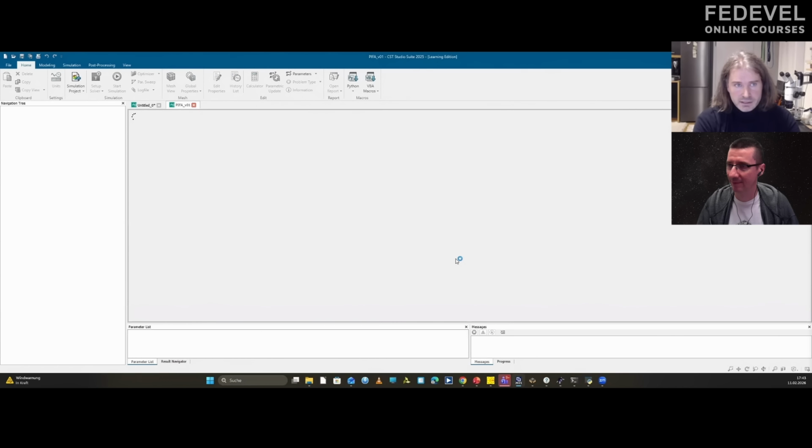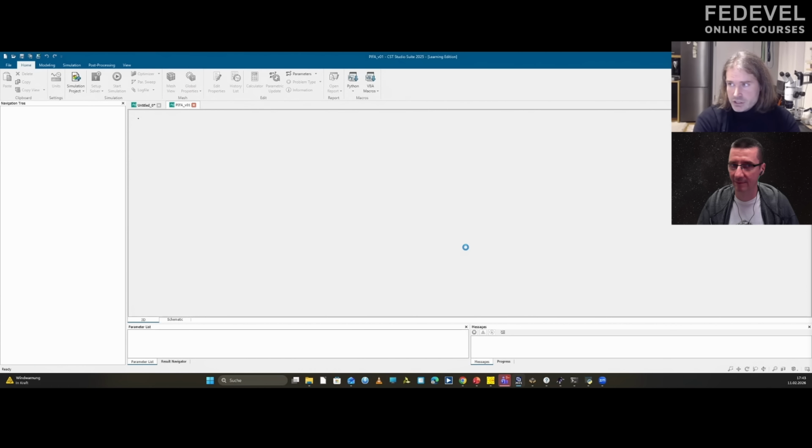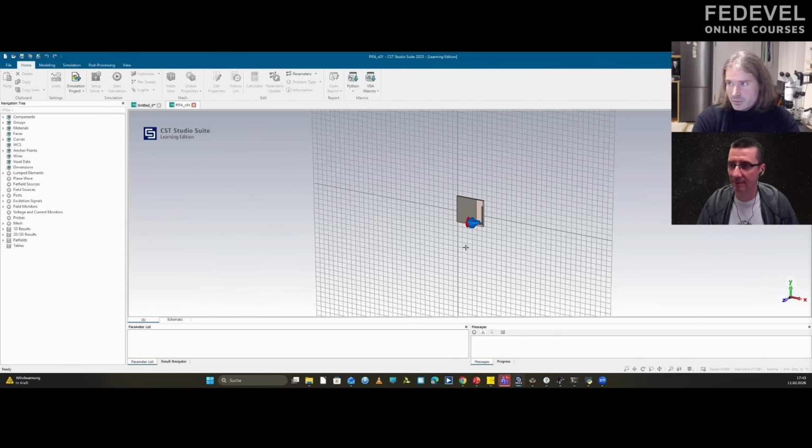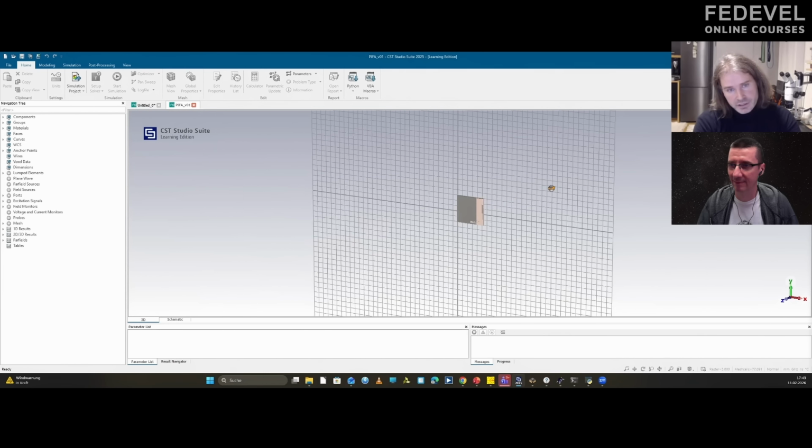So one antenna design which is very often used is the PIFA antenna, the inverted F antenna. It's a very cool antenna because the antenna is matched with the stub to the ground. It's like an inductor. It's a matching element in the end, which you are doing with that trace.